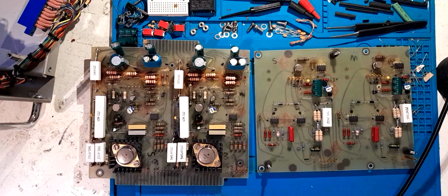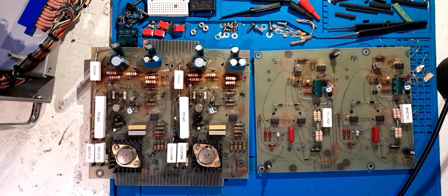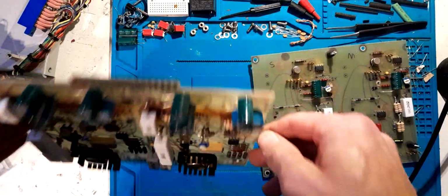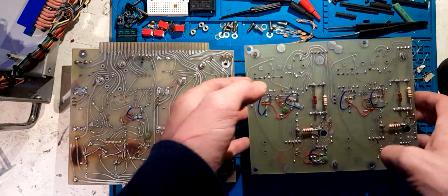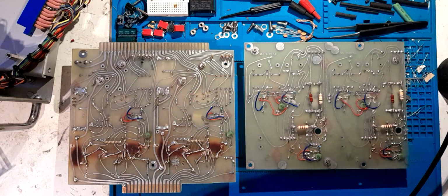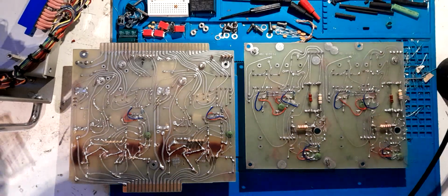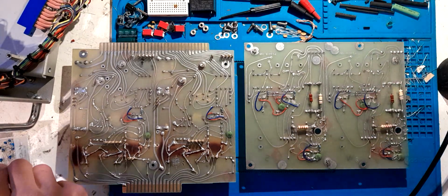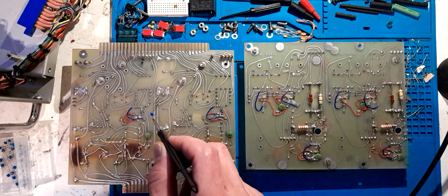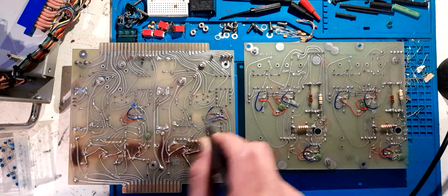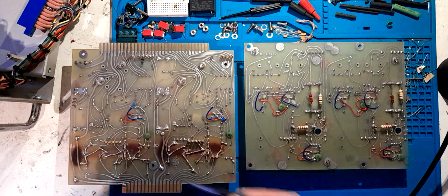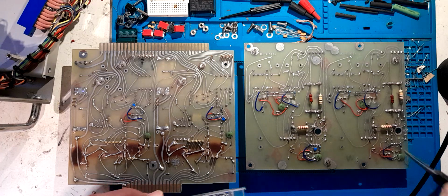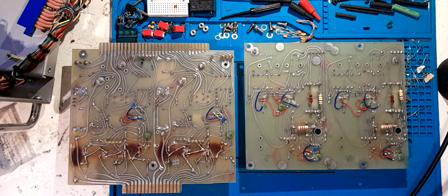Alright, I've just decided upon one more thing before I go ahead and put this all together. Since I'm going to be doing compensation on the opamps, I'd rather have everything how I intend on leaving it for its final state. I've weighed up my options, and I think what I'm going to do is put 0.1s right across each op amp. So that board's only got 2 op amps, that board's got 4, so that board's got 6.